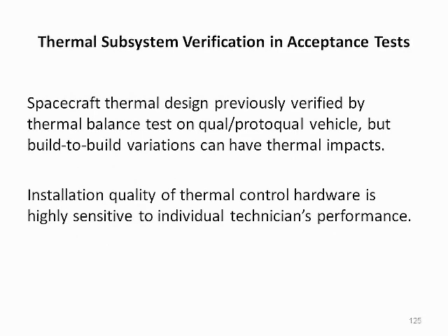For spacecraft undergoing acceptance testing, the spacecraft thermal design has previously been verified by thermal balance testing of the qualification or proto-qualification vehicle, but build-to-build variations can have thermal impacts because the installation quality of thermal control hardware is highly sensitive to individual technicians' performance. Therefore, workmanship verification is still important and must be accomplished during spacecraft acceptance testing.